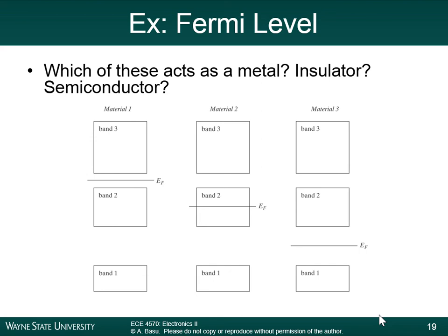If you ever see a band diagram that looks like this, where the Fermi level is situated within the band, that is a very conductive material. How about band 3? It's empty, so band 3 does not conduct electricity. Band 1 does not, but band 2 is responsible for the conduction.